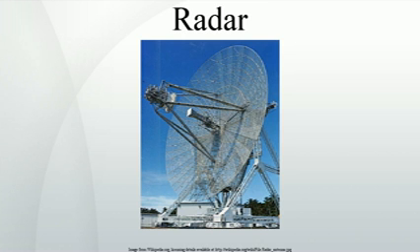It is possible to make a Doppler radar without any pulsing, known as a continuous wave radar, CW radar, by sending out a very pure signal of a known frequency. CW radar is ideal for determining the radial component of a target's velocity. CW radar is typically used by traffic enforcement to measure vehicle speed quickly and accurately where range is not important.